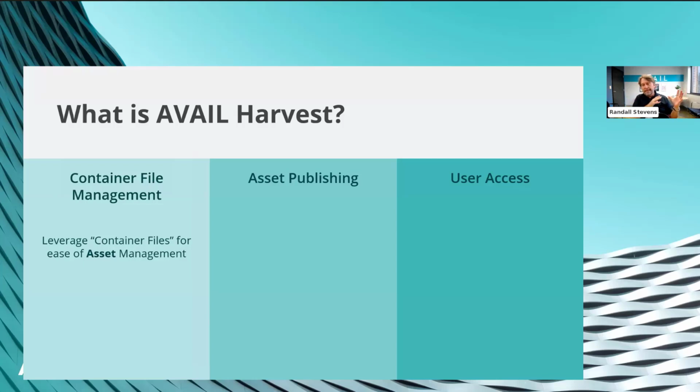So in Revit, usually families in Revit, if you're familiar with that, live on their own because they can be stored as these .rfa files, but there's a lot of content that has to be in a project file in Revit. So everything that's basically not a family. Drafting views, sheets, schedules, legends, any of those kinds of assets, if you want to treat them like that, are ultimately stored in an RVT file.